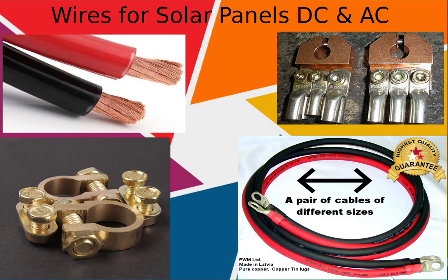When choosing the thickness of your wire, you can go one of two ways: a little thicker for safety, or just thick enough but vulnerable to sudden power surge. A great way to go about choosing the wire thickness for your solar system is to buy solar panel wire big enough to cope with the biggest current, amp, drawing appliance you have, and use that wire for all the other runs to the AC breaker panel. Use a wire sizing calculator for solar arrays that will figure out the size of wire you need. The insulation covering the wire can protect the cable from heat, moisture, ultraviolet light, or chemicals.